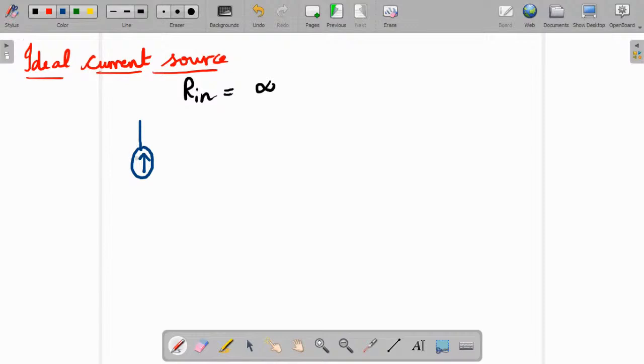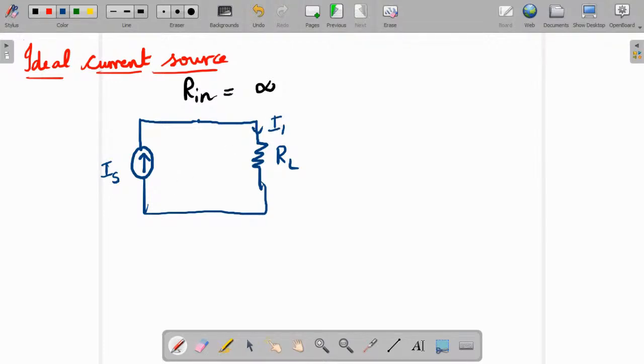For both AC and DC, the current source symbol is just this arrow mark. With a voltage source we can differentiate whether it is a DC or AC voltage source, but for current, unless they give it in the question, we will not know whether it is an AC or DC source. So this is RL. Let the current here be IL and the potential drop be VL.